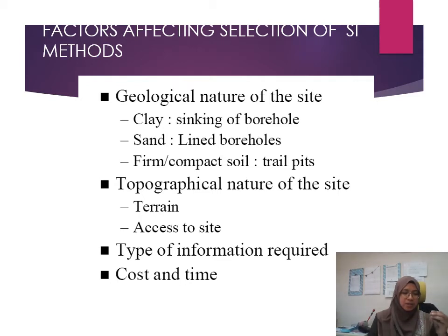So it depends on the type of topography of the soil of your site. You have to bear in mind the importance of how to move the exploration equipment into your site. For example, if your site is a hilly site, how are you going to move the equipment into the site?